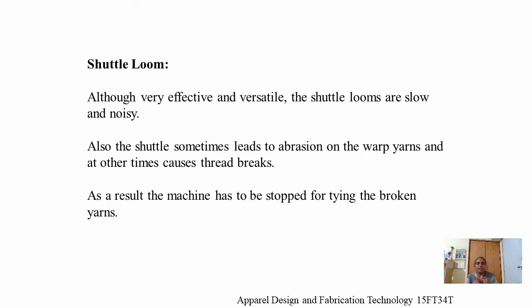The shuttle loom, related to the hand loom, is very effective and versatile, but it is very slow and it produces noise. The shuttle sometimes leads to abrasion of the warp yarns because it goes from front to back to insert the weft yarns. Many times it causes abrasion to the warp yarns.